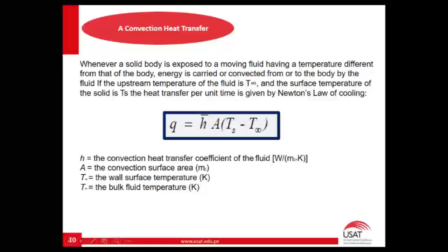Convection heat transfer. Whenever a solid body is exposed to a moving fluid having a temperature difference from that of the body, energy is carried off by convection from or to the body by the fluid, if the upstream temperature of the fluid is T infinity and the surface temperature of the solid is Ts.